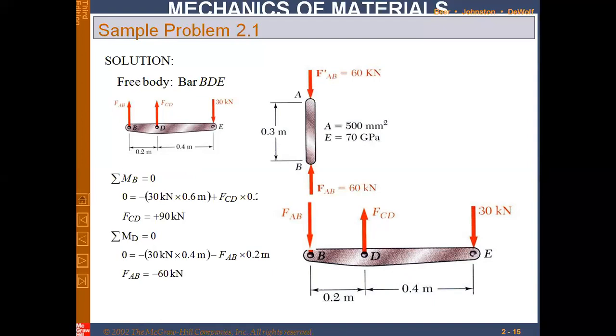So now what I'm doing, I'm bringing the link AB here. We have separated these links from each other. The force which the link is exerting on the joint is FAB. Conversely, the joint would exert the same magnitude of load on the link AB, but in the opposite direction.